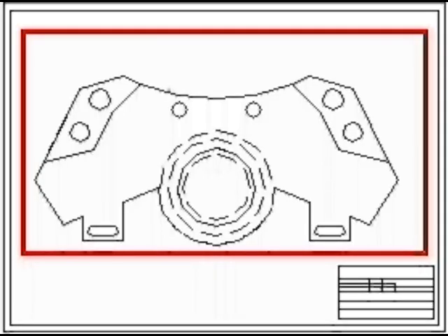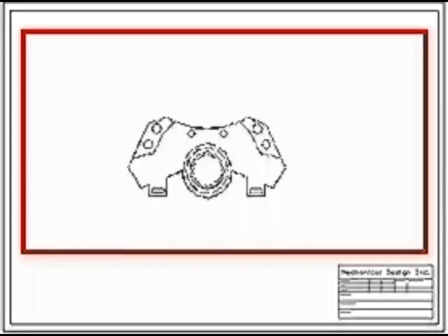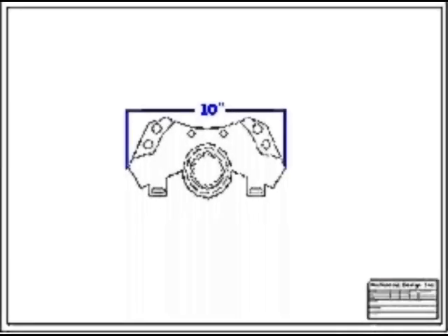To set the drawing scale, you first create a representation of your layout. Then, you define special areas on your layout to display views of your model. Finally, you set the scale for each view of your model. Always remember that you draw objects at full scale.